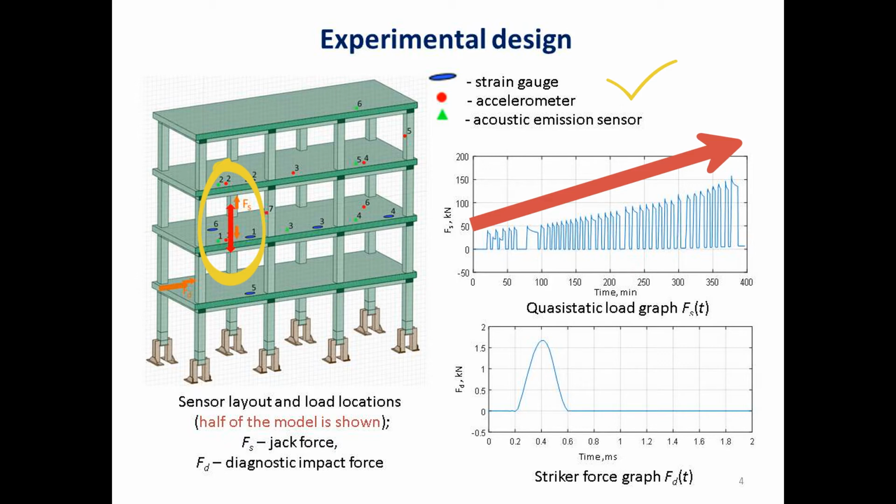The vibration diagnostic procedure is performed after each loading step when the structure is unloaded. Excitation of vibrations is performed using a striker of 470 grams. The place and direction of the impact is shown by the orange arrow. Acoustic emission signals are recorded continuously, excluding the impact period.